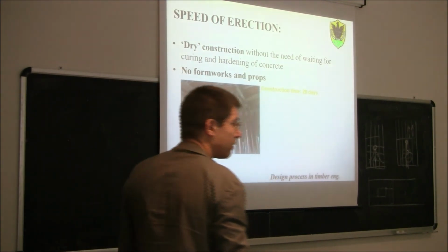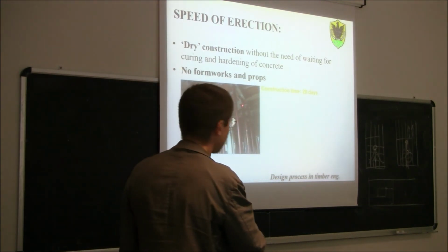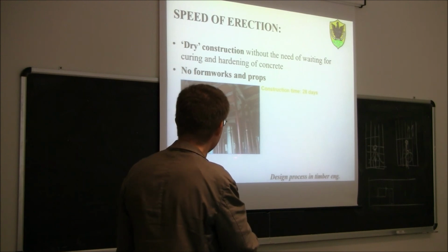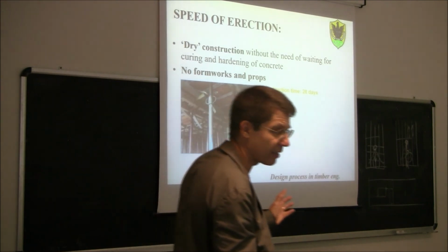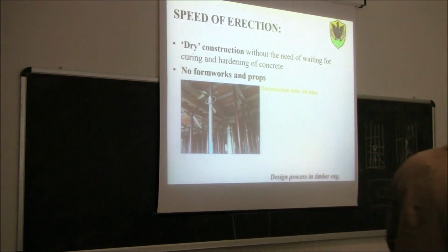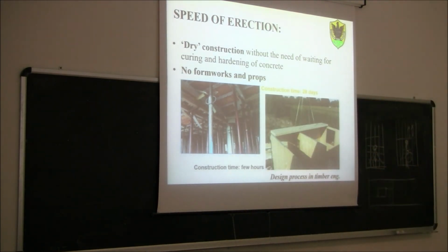If you remember, to construct a reinforced concrete floor, you need to put some props. You need to leave the props there for theoretically 28 days, and then you can take them out. For timber, you see, you put your walls, then you arrive with your timber panels, you screw them down. In a few hours, you can get your floor ready. Only a few hours.